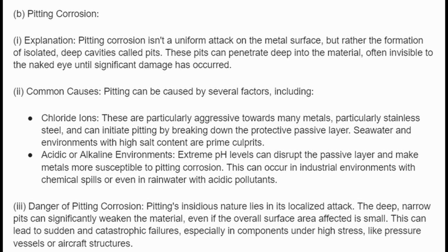3. Danger of pitting corrosion. Pitting's insidious nature lies in its localized attack. The deep, narrow pits can significantly weaken the material, even if the overall surface area affected is small. This can lead to sudden and catastrophic failures, especially in components under high stress, like pressure vessels, aircraft structures.